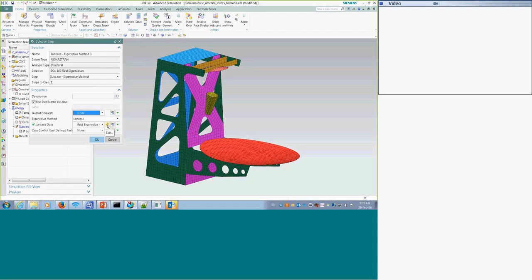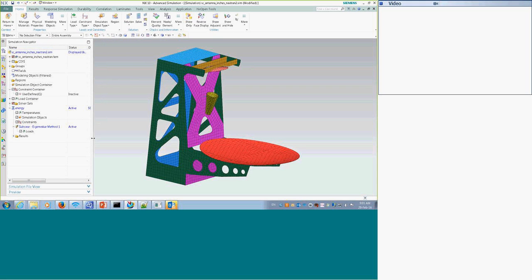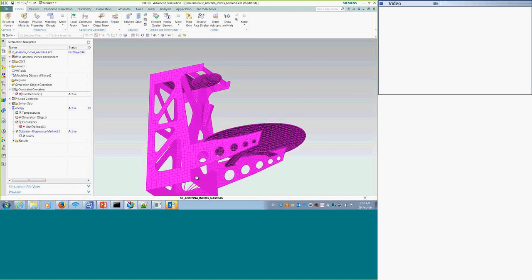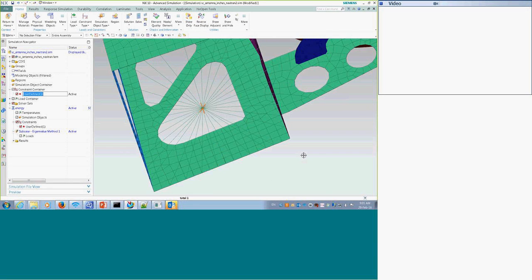By default, the first tested and that is. I'm just constraint here. So I had a single constraint at the base of my structure. This is important. If you're doing excitation, you're really exciting a single node and connecting that node rigidly to the interface points on your structure.